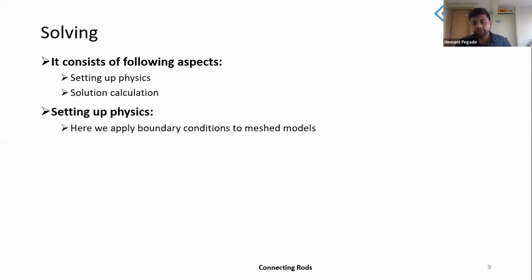The boundary conditions that I mentioned initially are basically your inlet boundary, outlet boundary, wall boundary, and the surface of the component that you are going to simulate. Basically whatever your physical components are, and whatever the walls of the system are, those are defined essentially to constrain the system, to complete the system, to make it realizable, right?